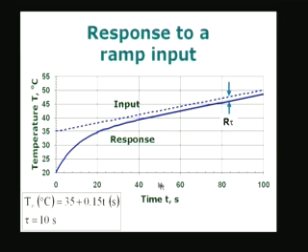If you remember, the time constant is 10 seconds, so after about 50 seconds, that is 5 time constants, the two graphs are going to become parallel. They are both going to be linear, but with a small difference r tau. In this case, r is equal to 0.15 and tau is equal to 10. Therefore, r tau is equal to 10 multiplied by 0.15, so a 1.5 degree difference is there. The difference is 1.5 degrees between the temperature of the ambient, which is changing according to a linear relationship, and the temperature indicated by the sensor.